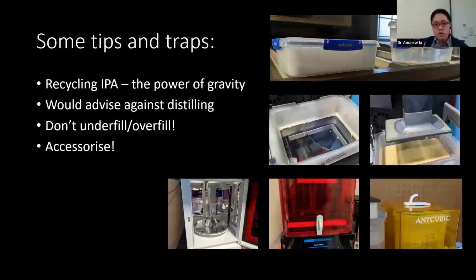Once again, do not underfill, do not overfill. Resins are expensive. Anything in dentistry is expensive. So you really don't want to overfill your things, but at the same time, you really don't want to underfill your tank as well. Otherwise, you will get a failed print, just like on this image on the left-hand side. I didn't put enough surgical guide resin there.